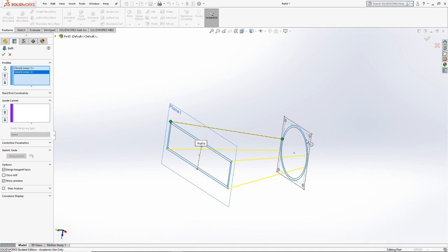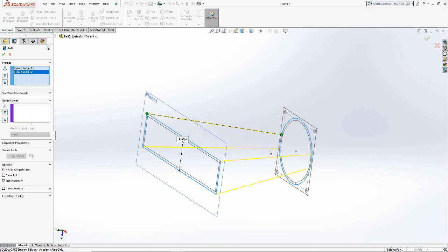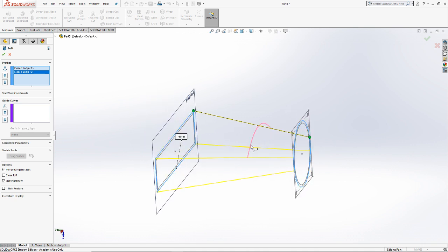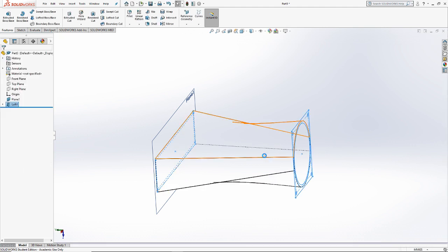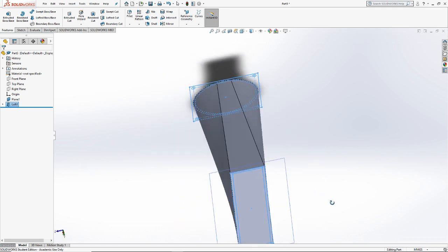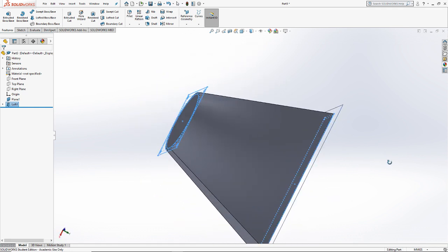So my SolidWorks on this computer was set up to not show the selection manager. So when I clicked on the shape, it just grabbed the entire sketch. Luckily for us, that was a learning opportunity to learn how to re-show the selection manager. Once we got the selection manager back up, this is, of course, the easiest extrusion to create. Now, if I click OK, it connects that geometry in the easiest way that it can generate. So the least complicated extrusion is what it creates.